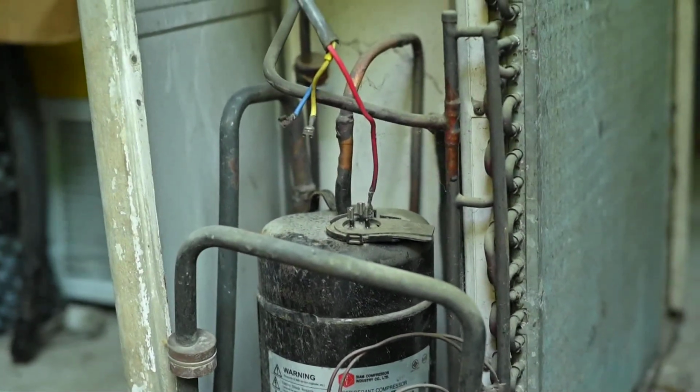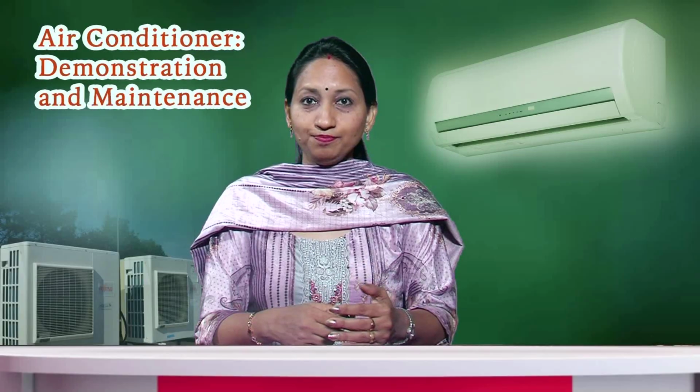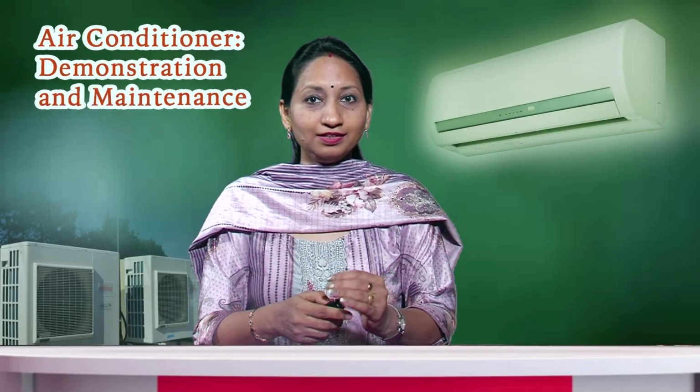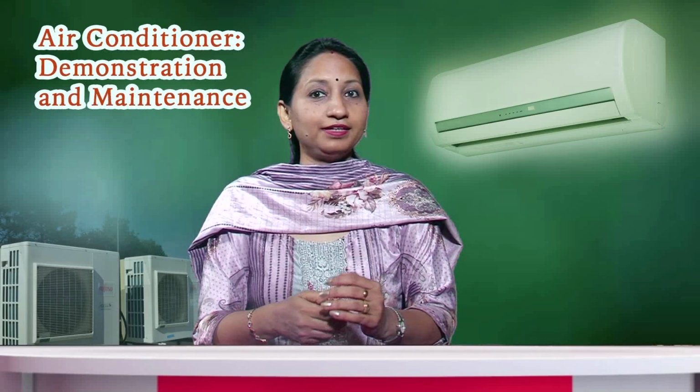inspect the coils. It is essential to wash or brush the AC unit if it is dirty. Alternatively, you can use a chemical cleaner for the coils. Remember to turn off the power by disconnecting the circuit breaker and also turning off the thermostat before cleaning.